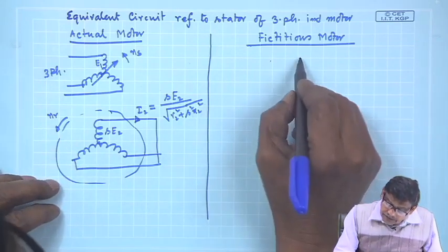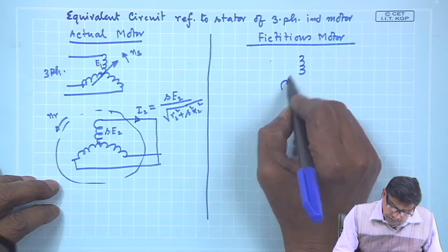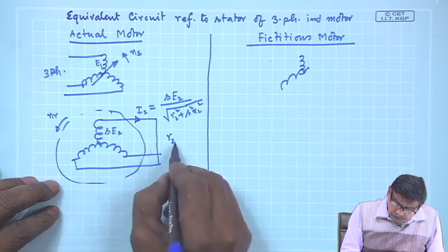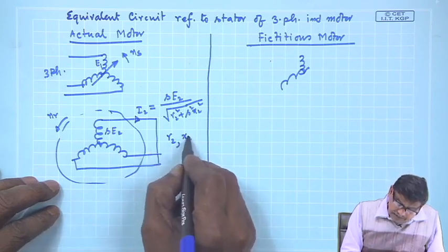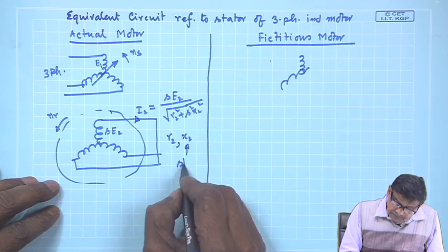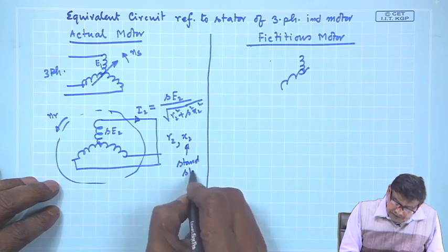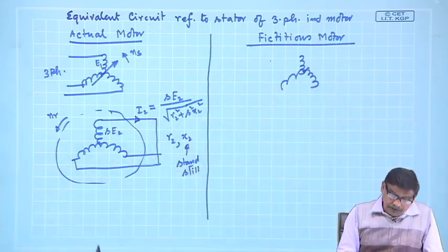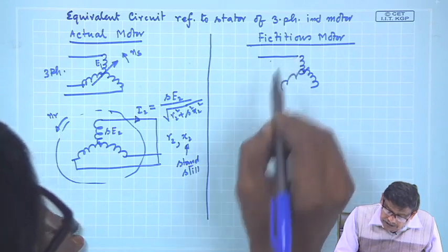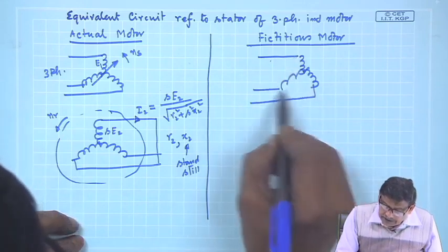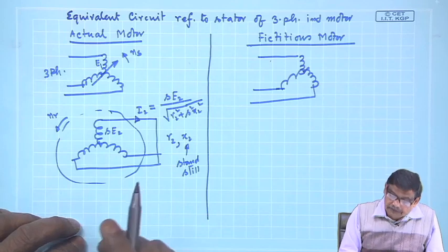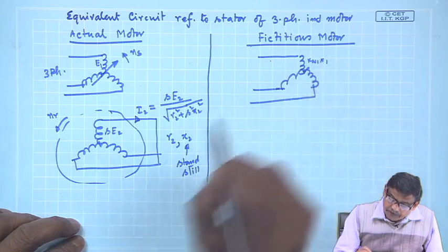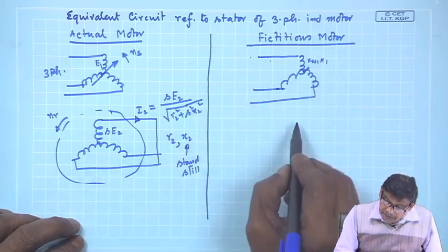Now, consider another motor. This machine has its winding resistance per phase R2 and standstill rotor leakage inductance X2, as before. Consider a fictitious motor; here the rotor was moving. What I will do is connect the same supply, and the stator is identical, with the same number of turns, Kw1 N1, the effective number of turns, and the same voltage applied.